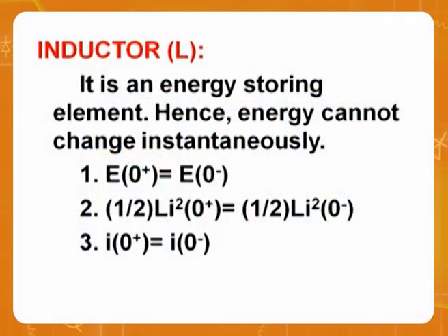Now let me take you to the inductor. When you talk about an inductor, it is an energy storage element, as I just mentioned, and hence its energy cannot change instantaneously. It takes some time. It needs some time. 0 plus, 0 minus. That means whatever is there just before switching, the same thing should be there after switching. You can't have two values.